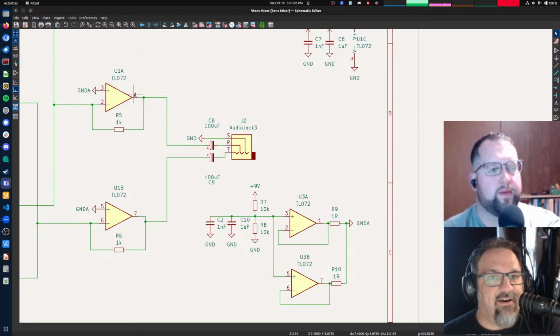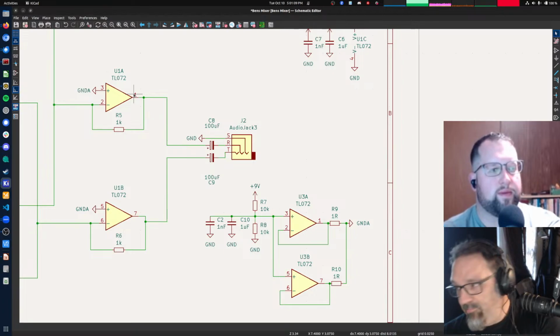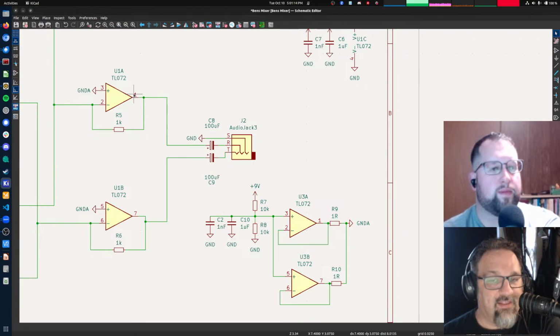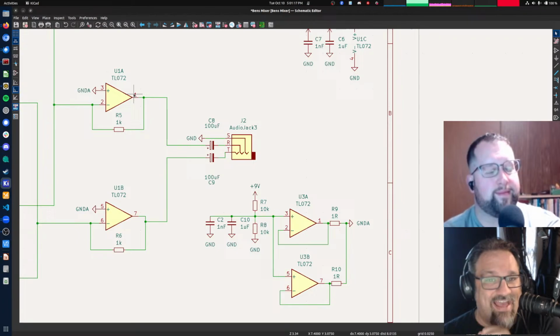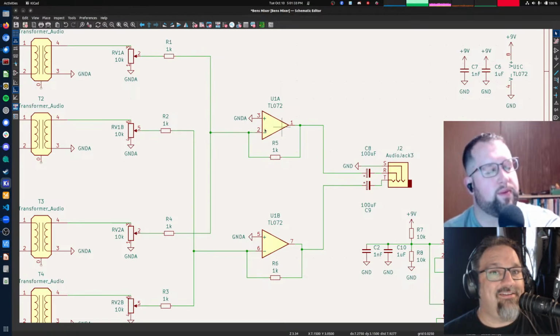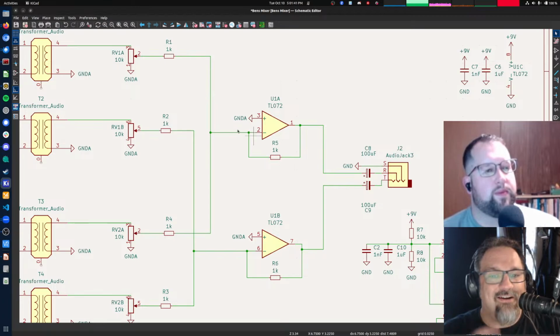And those capacitors there are a good way of basically covering up the little bit of DC voltage that an op amp is always going to cause. That's especially important if you've got 2 op amps in series. Let's say for some reason you needed an op amp over here as well. And if that op amp output a little bit of DC voltage, and then you came over here and gave gain on this op amp, whatever, let's say it had 1 millivolt of DC voltage coming in here, and you had a 10-to-1 gain here, then this would be putting out 10 millivolts of DC voltage.